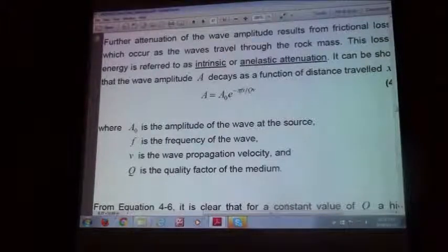That would distort the energy and give you a bad image of the source. So that's another difference from earthquake seismology. There we can pretty much use all your sensors that have got decent recordings. Here we have to take into account the effect of our excavation on our ray paths.